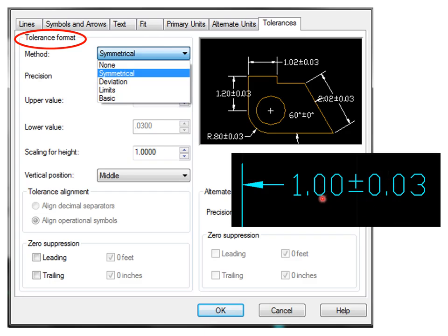So here you're telling the machinist that from the 1 inch thickness, you can be off by 0.03, or 0.030 thousandths of an inch, in either direction. This is the wiggle room you give the machine shop and also the inspector. When the inspector measures the thickness of the plate that was machined, they want to know how much they can be off by, and that's referred to as a tolerance. Again, we'll talk more about this in a later chapter. Next slide.